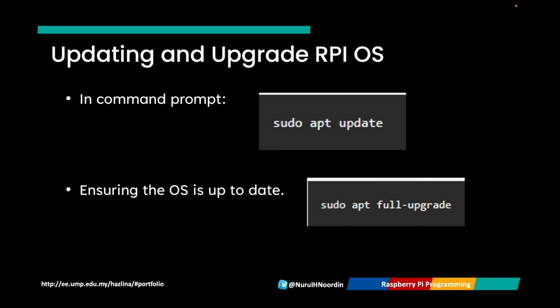Open the terminal on Raspberry Pi, type the following command and press enter: sudo raspi-config. Navigate to the interfacing options and enable SSH, I2C, and SPI. SSH allows remote access to the Raspberry Pi. I2C and SPI enable communication with sensors and other hardware components. After enabling these options, restart your Raspberry Pi to apply these changes.